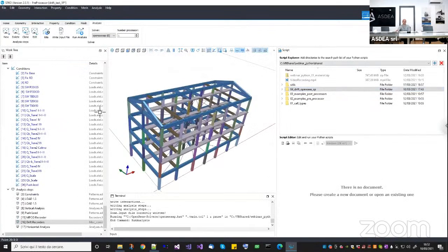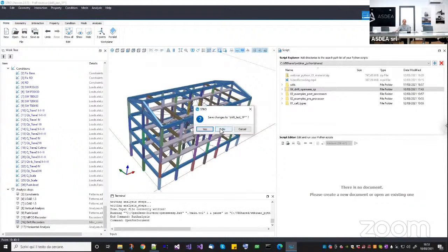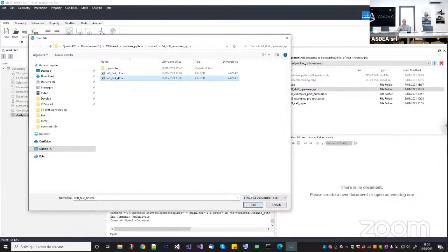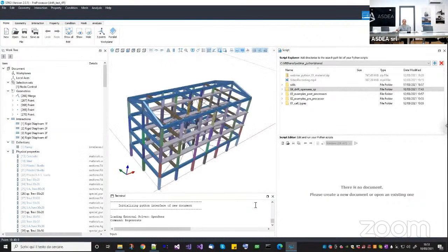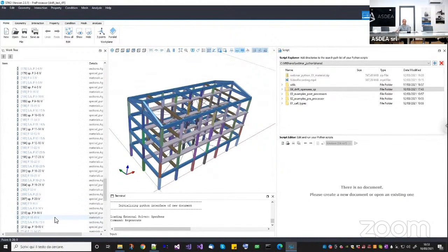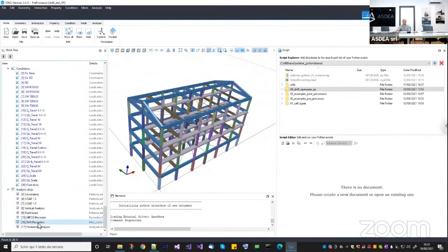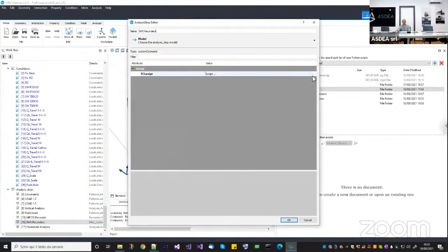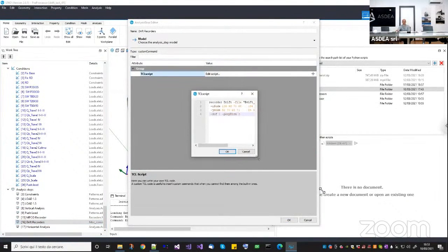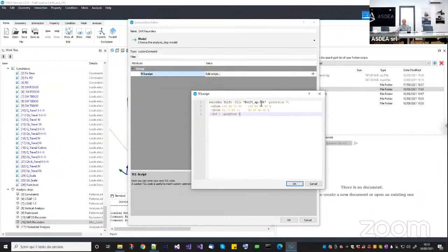And now I try to do the same, but with OpenSeesSP. Now imagine this model was a very large model, so you actually needed parallel processing. So I open the other one, which is OpenSees test for processors. As I said, the file is exactly the same. The only change I made is on the drift recorders, because instead of calling it drift, I call it drift sp.txt. Why? Just because I want to compare them and show the differences.